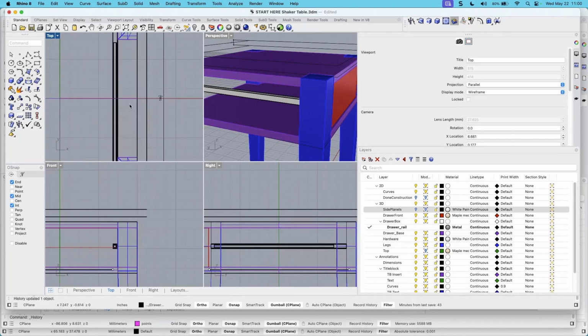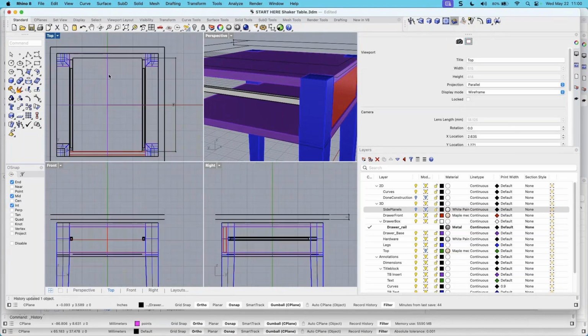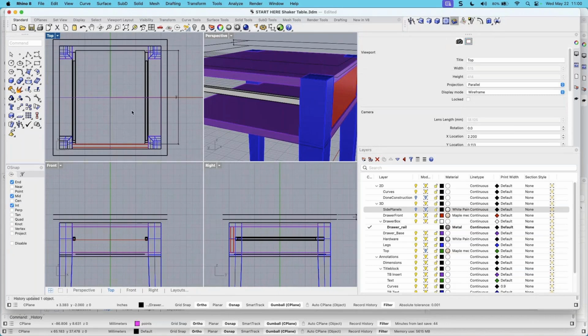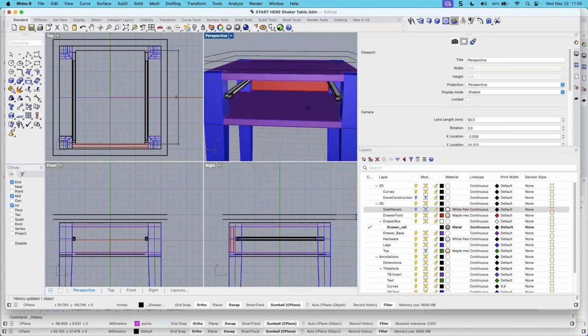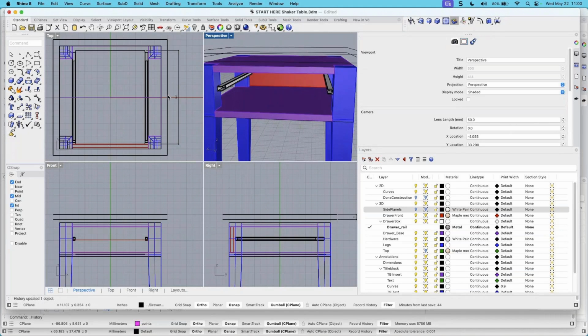The thing to understand about Rhino is it'll be as accurate as you want to be, okay? A lot of times people just model and they don't care too much what size things are. Rhino's good for that. But if you want to be accurate, you can get there. Rhino will be extremely accurate up to 16 or more decimal places, which is something you probably won't be able to manufacture to. So then you start getting into double floating point errors, and anyway, it'll do more than you need, I'm sure.